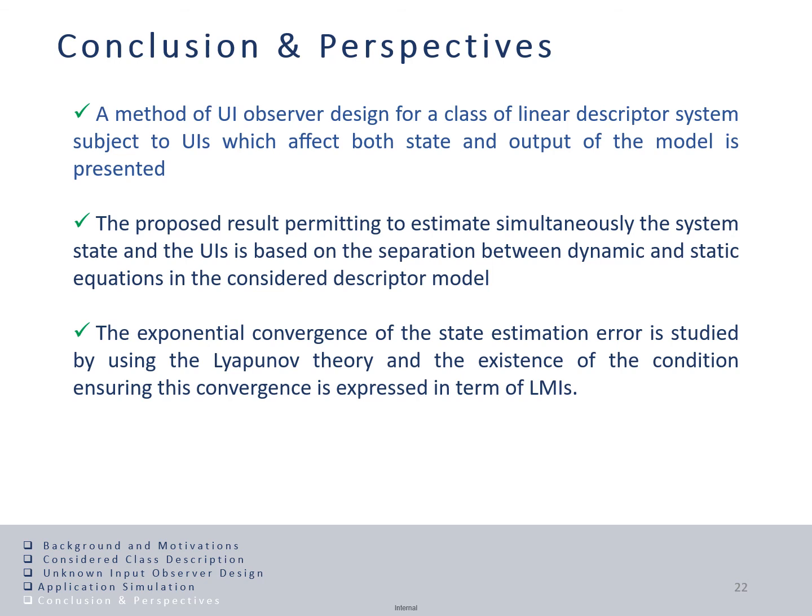The proposed result, permitting to estimate simultaneously the system state and the unknown input, is based on the separation between dynamic and static equations in the considered descriptor model. The exponential convergence of the state estimation error is studied using the Lyapunov theory, and the conditions ensuring the convergence are expressed in terms of linear matrix inequalities.